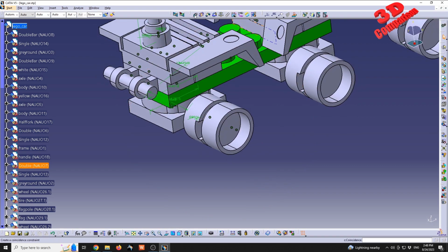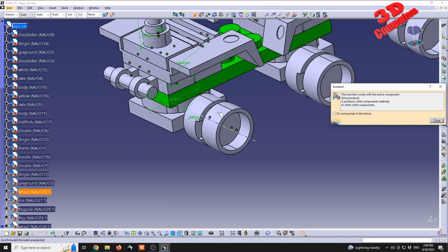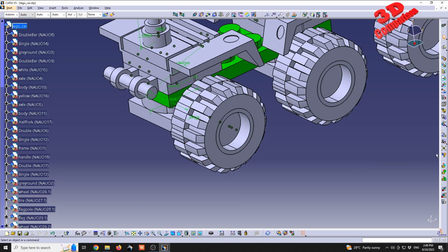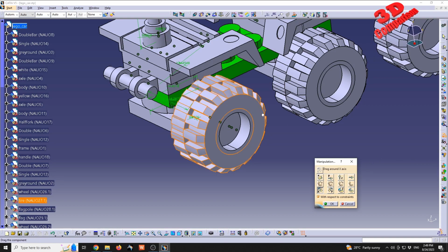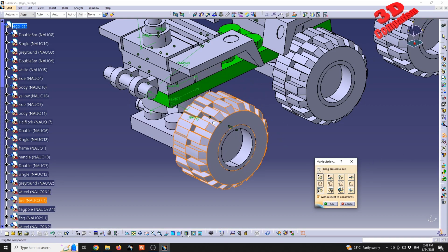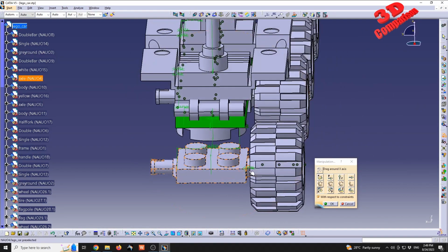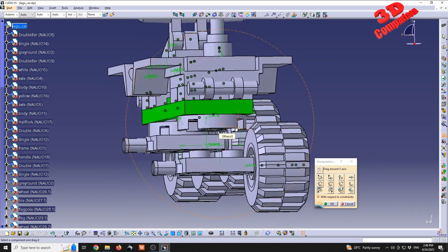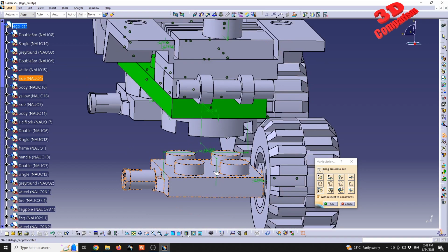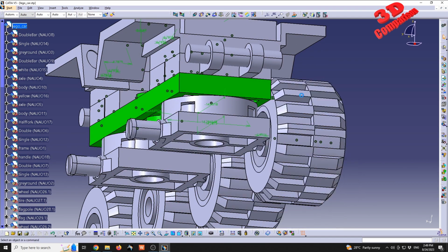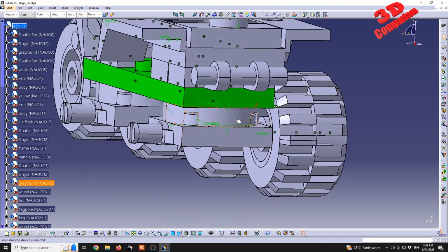And that means I'm gonna go with coincident constraint. We know that this axis should be the same with this axis. I'm gonna send that back. And if I'm gonna try again to manipulate this, on the x-axis, we can still see that even though they will always maintain that offset, there is no plane coincidence between those. So we're gonna need to add that bottom floor with that section to fully lock that.